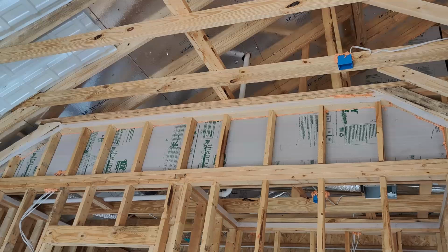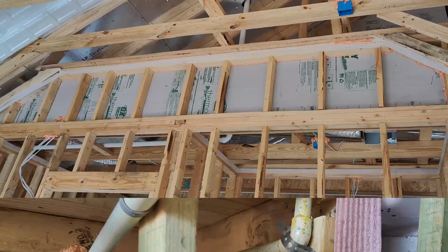If the walls or interior are cold enough, and hot attic air is able to transfer easily through insulation, it can reach the interior sheetrock, which is a lot colder, and could lead to condensation inside the knee walls. Another reason why you keep air out of knee wall insulation and out of any others that are exposed to unconditioned spaces.